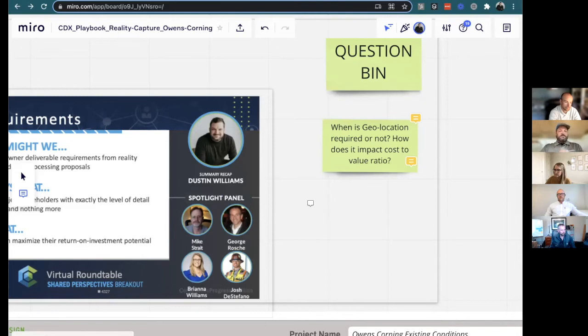But then when you get inside the building, the problem that you get into is that people are tying their models together. They're using an Inventor, they're using a PDMS system, they're using a SolidWorks, and those systems do not like coordinate systems when you start talking about putting a true elevation onto a machine drawing. It just doesn't work out. The systems puke on it. So you immediately are caught into that you've got to go to a relative coordinate system inside the building.